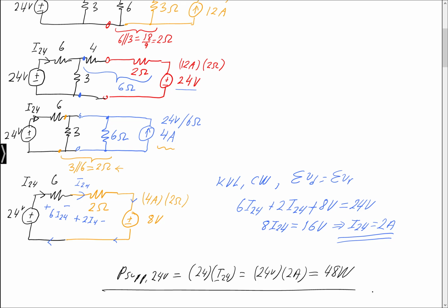It's a lot more difficult to make mistakes when you redraw the circuit consistently, rather than just using equations, where it's a lot easier for mistakes to sneak in, a plus sign sneaks in, a minus sign sneaks out, subscripts drop out, things like that. So that's why source transformation is quite a nice method to keep in mind to simplify circuits. Okay, so let's do another one.